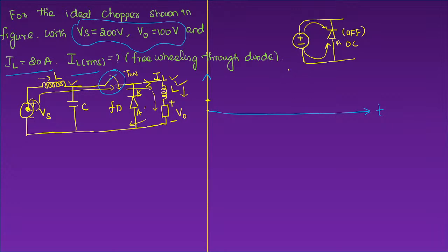This is the first case. In that moment, the switch is turned on and current starts charging. So this inductor is slowly accepting the changes, because of this the output current is slowly charging. Remember one thing, sir, how are you starting directly from some value, why does it not start at 0? The very first time you switch on this circuit, it will start from 0. From the next cycle onwards, it will have a certain amount of initial residual current.